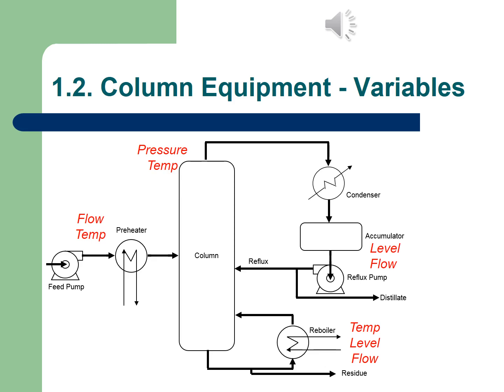The pressure and temperature of the column also need to be controlled. The pressure will have an effect. If the pressure increases, it means that basically your boiling point is also going to shift. Just to give you an example, if we're going to boil water, say for instance here in Gauteng, and we're going to boil water, say for instance at Mount Everest, that is a lot higher above sea level, the pressure, say for instance at Mount Everest, is going to be less on the surface area of that water. So it means that you will actually boil then that water at a lower temperature.